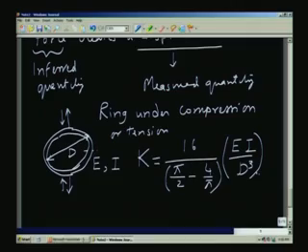So, what is common in all the 3 cases we have considered now, 3 or 4 cases? The commonality is that force is now converted to a displacement and the displacement is measured, and from this you work backwards, knowing the spring constant of the particular system, either a regular spring or one of the structural members, we can find out what the force is.